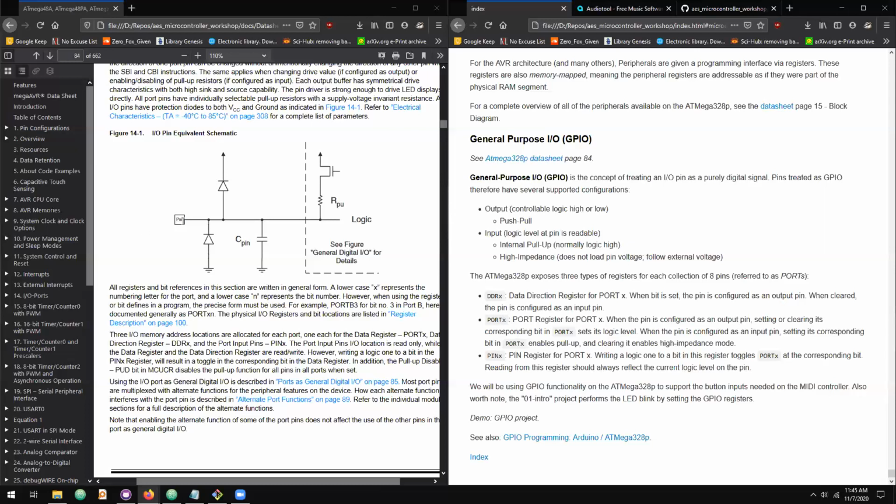And this is really helpful for having a very quick instruction that will do this pin toggle, because the other way we could do a pin toggle is we could read its current state and then apply the bit level that's exactly the negation of the current level, which equates to basically two commands rather than one.